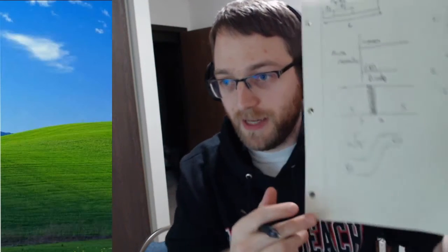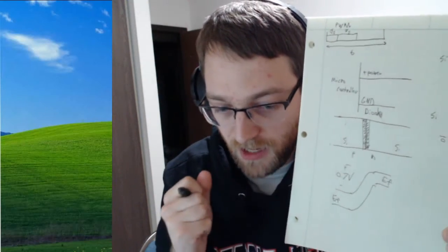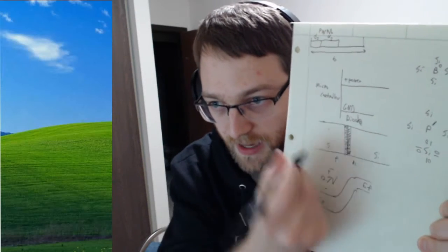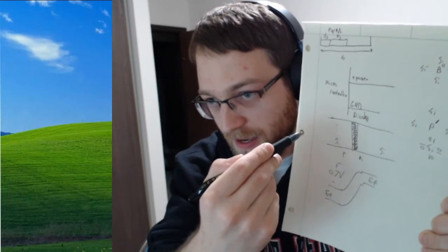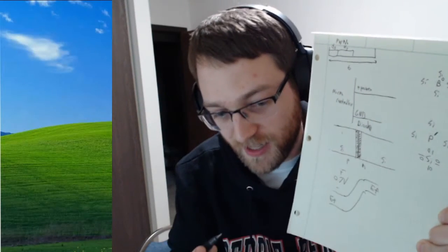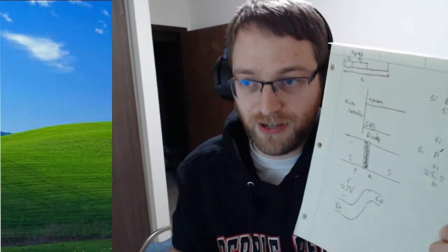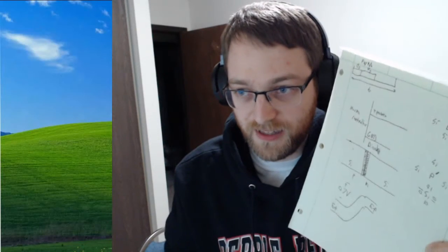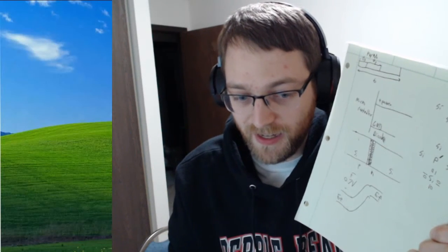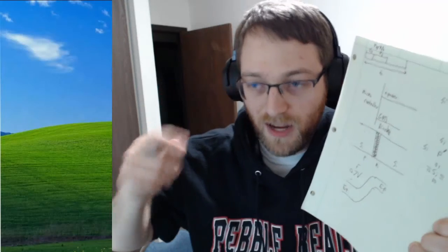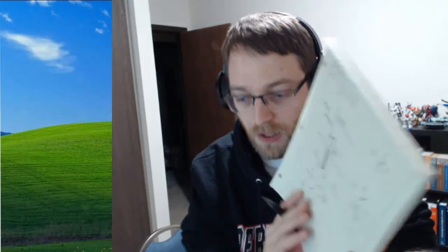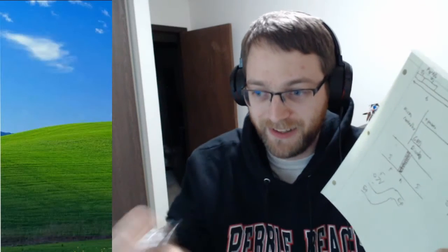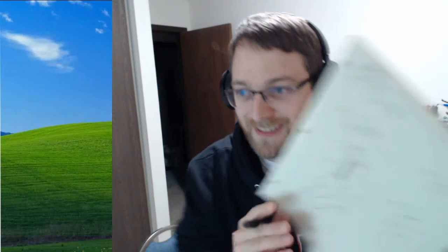And a lot of times, with the current and voltage you're putting in, it gives too much energy and an electron jumps too high. Then after it crosses the gap, it needs to drop back down into a convenient place for it to be on the other side. So it shoots out a photon, and then it drops into its comfortable energy level. And those photons are emitted by the light-emitting diode as light.